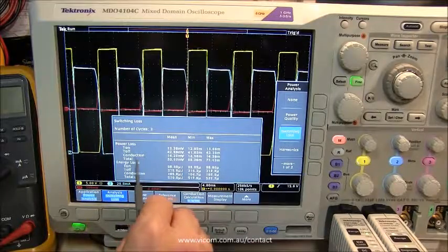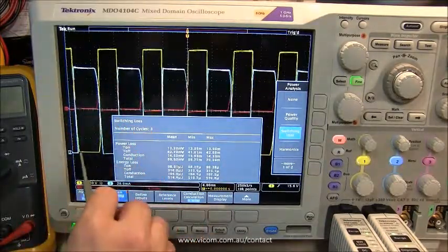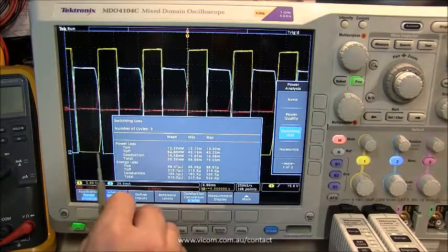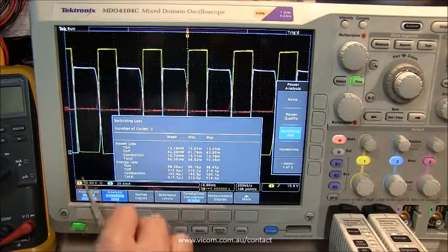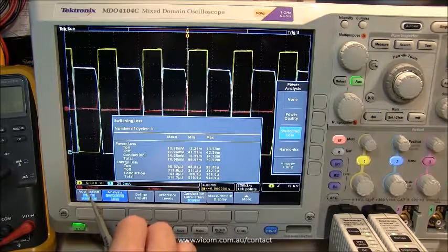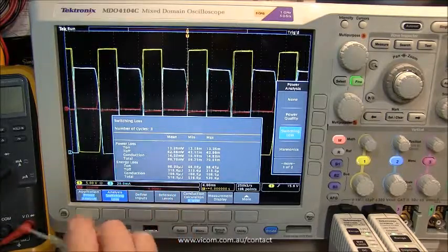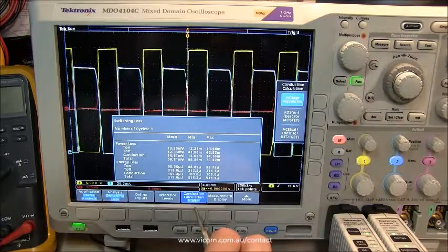The conduction loss is computed by multiplying the current through the device by the voltage during the on time. This voltage during the on time can be quite small. Measuring this accurately can be problematic when dealing with relatively large voltage scales. Using high-res sampling can certainly help this. But in addition, there are several other conduction calculation methods that can be used.